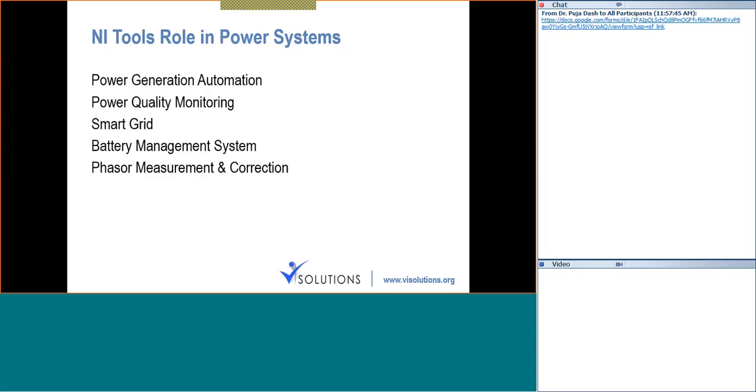And more importantly, when you have several places where you generate power, you need to synchronize these waveforms, the type of waveform you generate. Synchronization is very important. And due to transmission, you have inductance and capacitance effects, and due to that there will be a lot of phase difference.